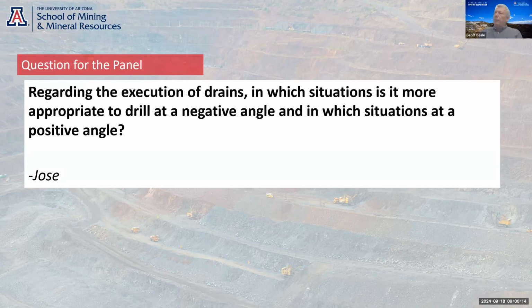There's also a tendency in some environments to drill drains too deep. I think in the course, if you're trying to achieve some general dewatering and general drainage, then deeper is better. But if you have a particular structure or a dilated structure shallow in the slope which you're trying to depressurize, then you just need to reach that structure. And if you drill too deep, you could bring water from further back in the slope into that structure. Yeah. So not only the position of the target, the depth is also important.